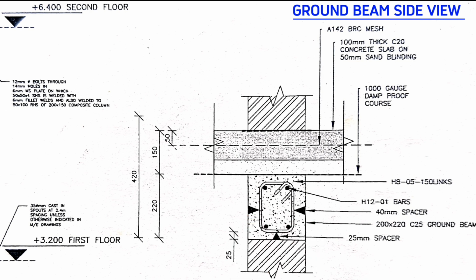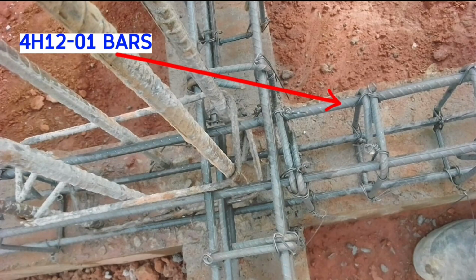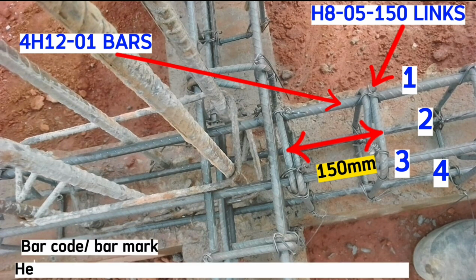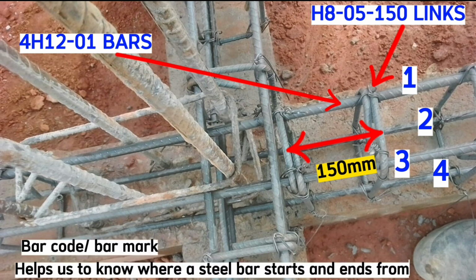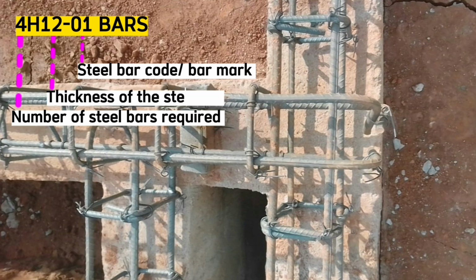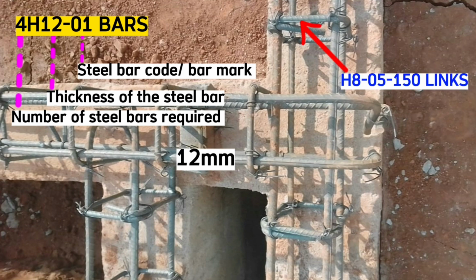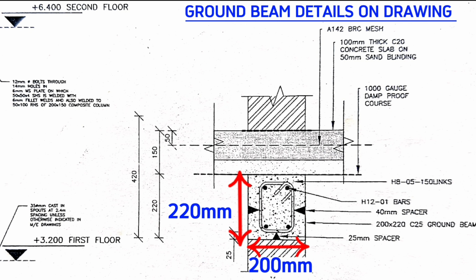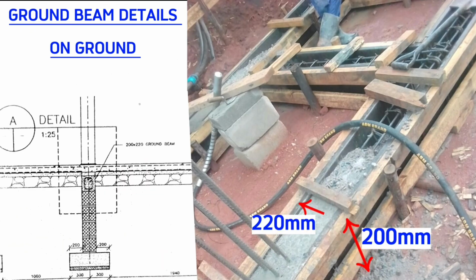The drawing also directs us to use 4 H12 code 1 steel bars with H8 links at a spacing of 150mm. These are the 4 H12 steel bars. This is 1, 2, 3, 4 and these are the H8 links at a spacing of 150mm. This code 1 just helps us to know where a steel bar starts and ends from. H simply means the thickness of a steel bar, therefore H12 means that these bars are of thickness 12mm, then H8 means that this bar is of thickness 8mm. The drawing also directs us that this ground beam is of 200mm by 220mm, so physically on ground this is 200mm and this is 220mm.